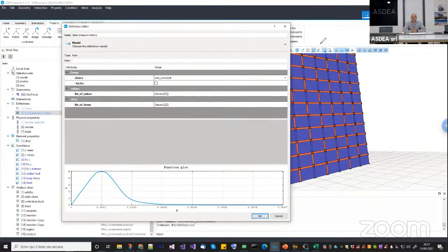Additionally, it would be interesting to show how to handle parallel and sequential explicit analysis. Of course, I decided not to talk about the parallel one here because in sequential analysis, as you've seen, I use the diagonal solver. Now there is also a diagonal solver for parallel analysis, which is called MPI diagonal. The problem is that it has a bug. I was trying to use it these days, but I've seen that there was a crash. Now I have to go inside the OpenSees code and try to find where that crash is. That's why I want to move the discussion on parallel explicit to future webinars.